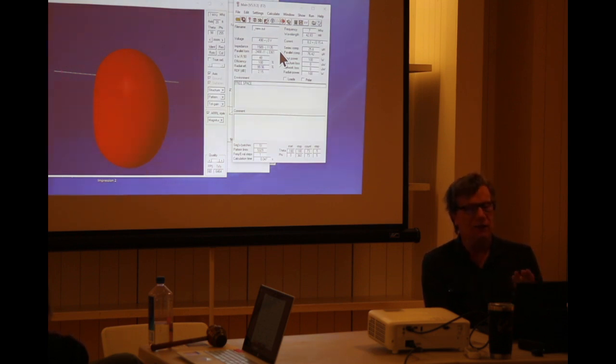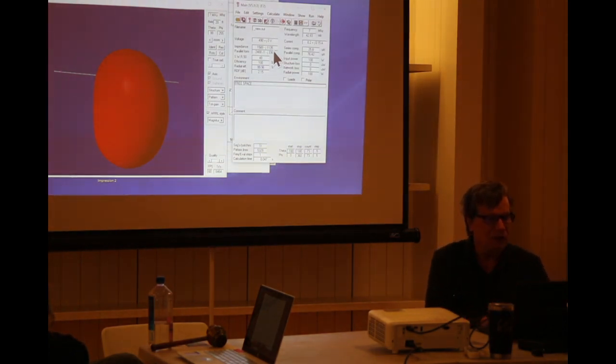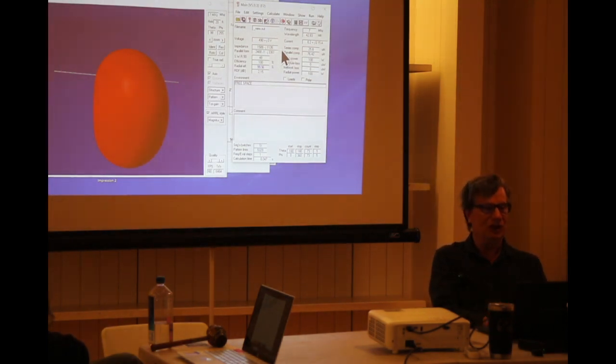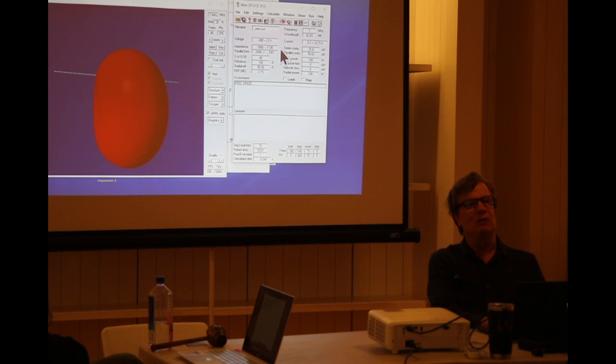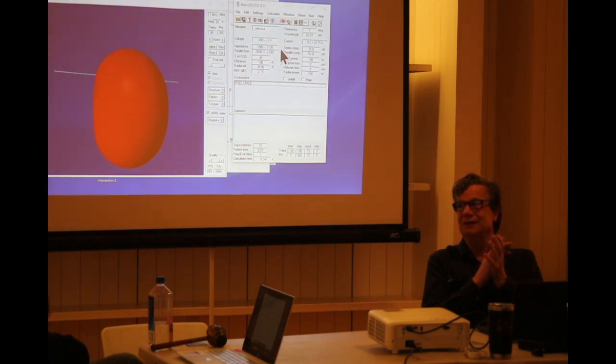Since we're at an end fed, we know we're going to be working with anti-resonance, okay? Since this is showing minus, which shows capacitive reactance, right? Minus J is going to be capacitive reactance. So what do we normally do with an antenna if we show capacitive reactance? Do we have to lengthen or shorten it? You would normally have to lengthen it, right?